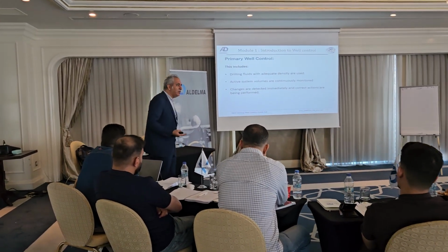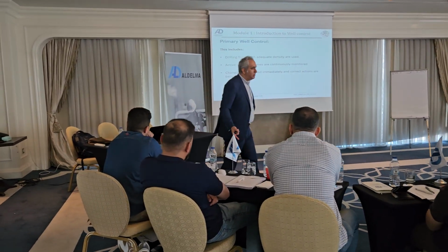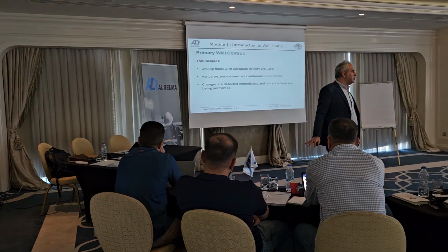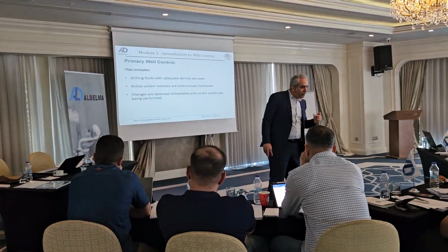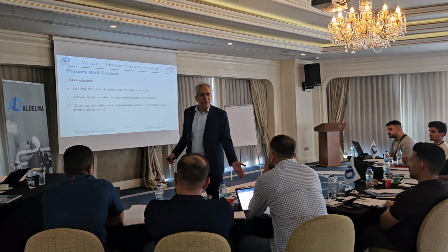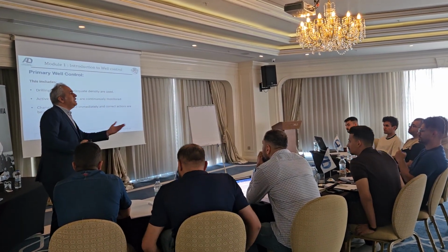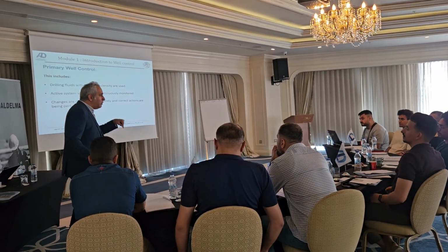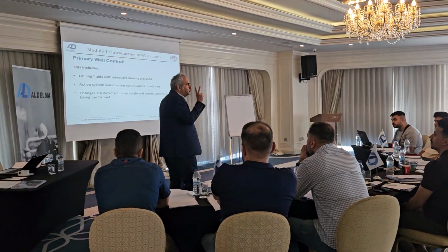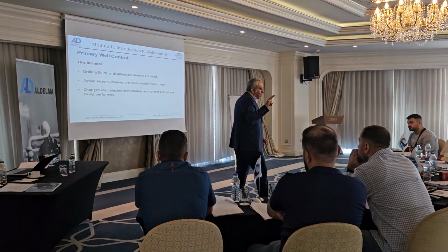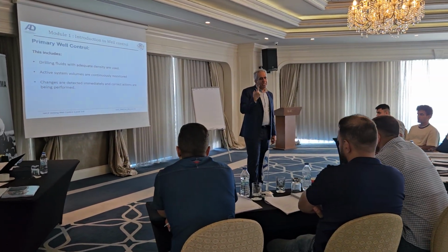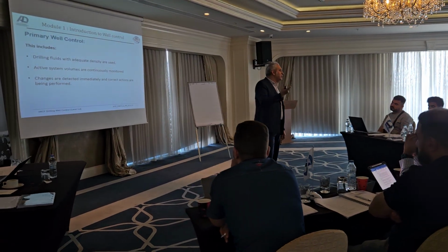Any increase in the flow, we need to stop and go for the flow check. If in the flow check we have flow right away, we need to shut in the well and then inform the supervisor. This is the job of the driller. I believe two people are very important in the rig. One is the driller, one is the mud engineer.